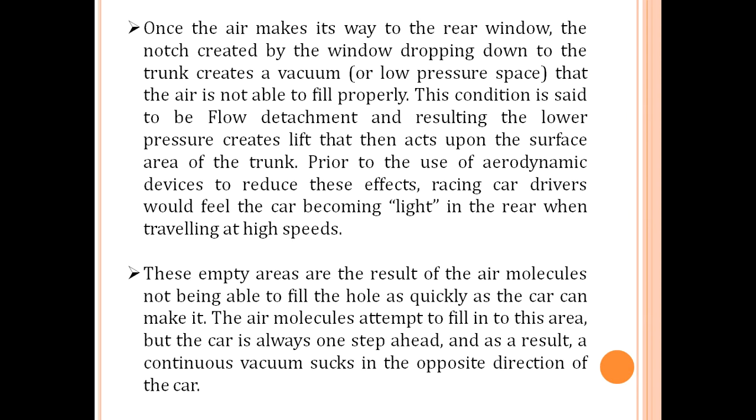Once the air makes its way to the rear window, the notch created by the window dropping down to the trunk creates a vacuum that the air is not able to fill properly. This condition is said to be flow detachment, and the resulting low pressure creates lift that then acts upon the surface area of the trunk. Prior to the use of aerodynamic devices to reduce these effects, racing car drivers would feel the car becoming light in the rear when traveling at high speed.